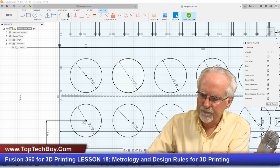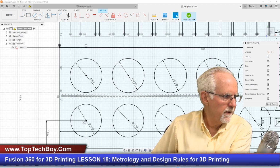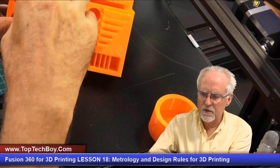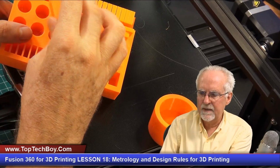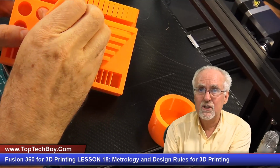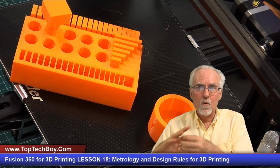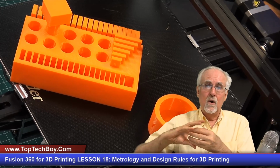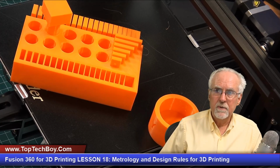So at 15.2, it is completely free to move and there's no wobble. At 15.3, it fits a little bit nicer and there's no wobble, but I'm just afraid there might be a few high spots on there. And as you work this around, it's probably going to rub a little bit. And so I'm going to say that if I want a smooth fit of a wheel on an axle or a hole on a pin, I am going to want 0.2 millimeter tolerance.